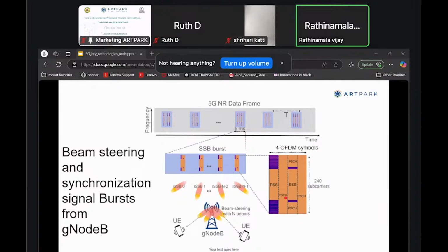Also the number of resource blocks available in the bandwidth, and the physical carrier allocated to the user equipment. All those details are sent in this physical broadcast channel. It also tells the UE when it can attempt to connect to the cell, and it periodically sends some reference signals and the current modulation schemes used, and so on.